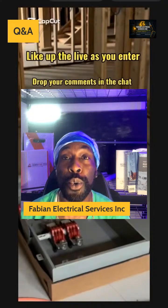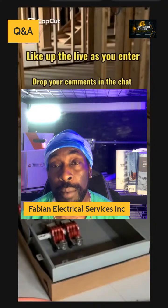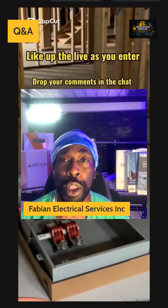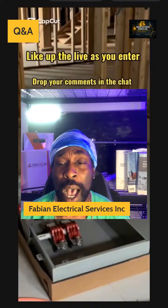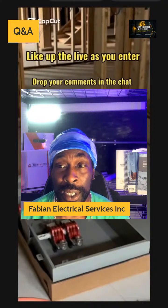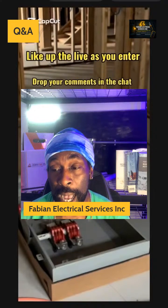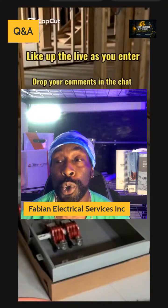So let's say you have 3 number 6s running inside of a conduit. Most guys will probably use 3/4. I went with 1 inch for the simple reason it's easier to pull. It's also a lot easier to breathe in. It has room to dissipate its power and so on.